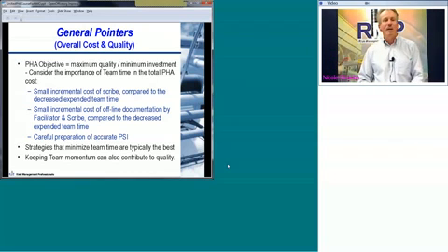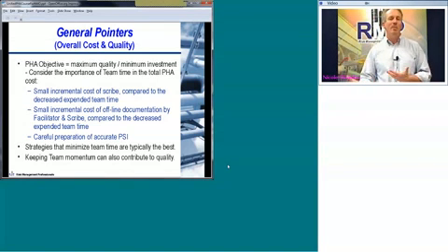When you're balancing the team size and who's involved, the scribe, yes, it costs a little bit extra to have that person assigned to it, but for that small incremental cost, you can get a big boost in team efficiency and the quality of the HAZOP study, and the facilitator can get some assistance in documentation, all of which can maybe lower the overall net costs of the project. It also provides an additional individual to help prepare and make sure that all the process safety information and background information is available for the team.